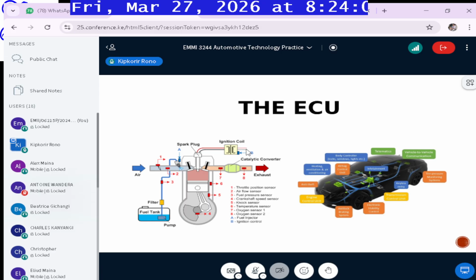So also, if that fan is malfunctioning, or there's a fault in that sensor, or the fan is not functioning, usually the heat loss process is not efficient, so the temperature can also rise. So it can also be a problem like that. So the temperature can rise for a number of reasons. So you always have to watch out for quite a number of things, especially near the cooling process of the engine. If the cooling process is not efficient, you'll have temperature rising.